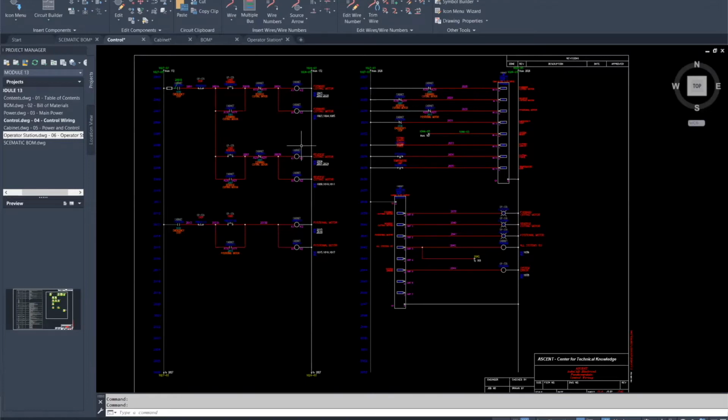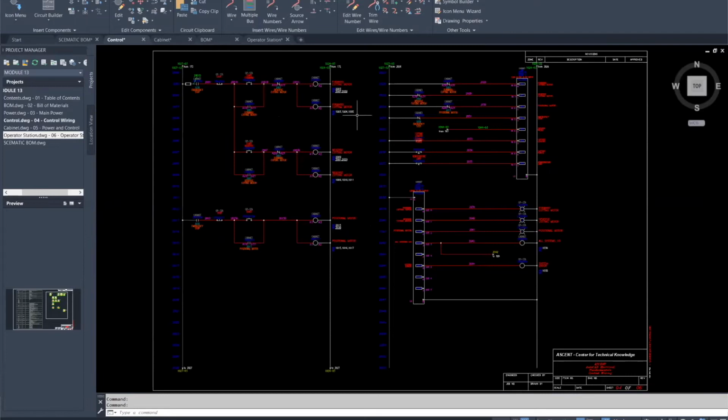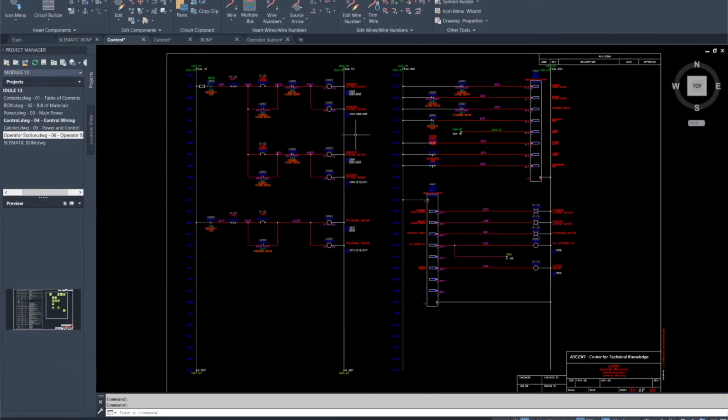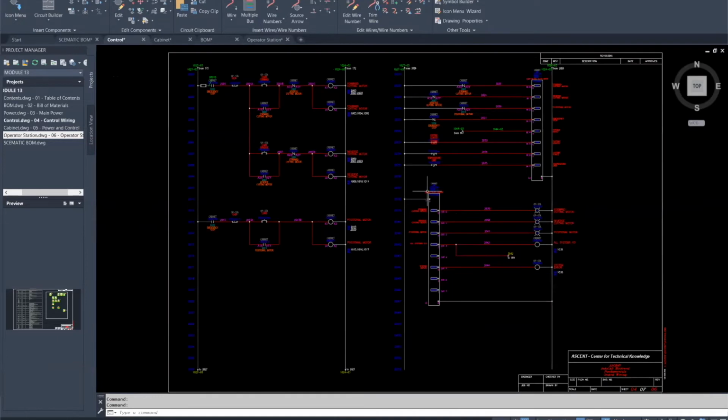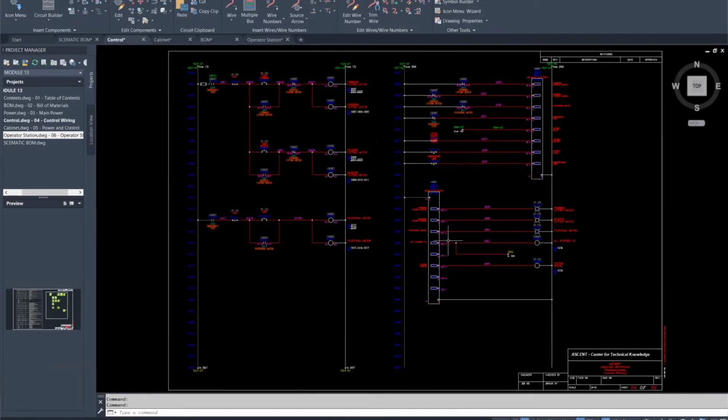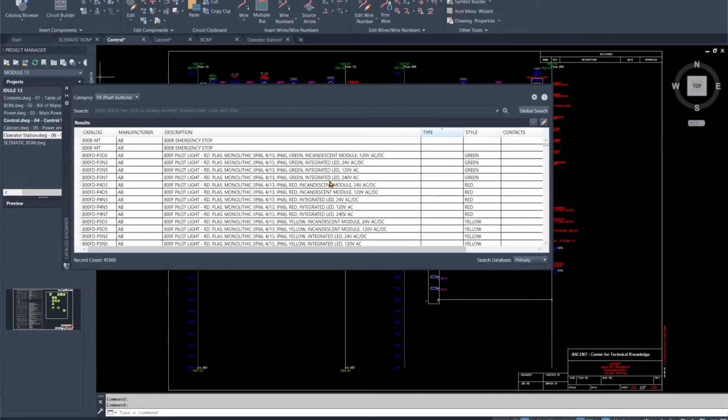And that's what you find. That's the productivity, time-saving thing about building custom components. The same thing applies if I use the same circuit over and over again. Like I always have this ladder with 2 PLCs put in here. I can save this ladder as a library component. And like I said, someone working across the world, accessing the same library, can put that ladder in and not have to redraw this circuit at all. So that's a real time saver for AutoCAD Electrical when building circuits: you can build library components and share those.